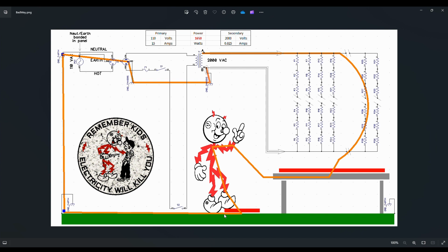Anyhow, the point is, why is this circuit even able to take this path starting out through here? Because it can come back through ground to this ground connection through your chassis to point B, which is where it desires so much to go. Now, if you have a plastic case, then you don't have this type of connection through your chassis ground.